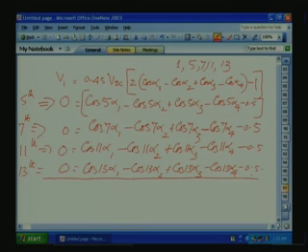Now take a case of general variable speed operation. Let's take that we are using harmonic elimination for a 3-phase motor control application where the frequency varies from 0 to 50 hertz, with a frequency resolution step of 1 hertz.